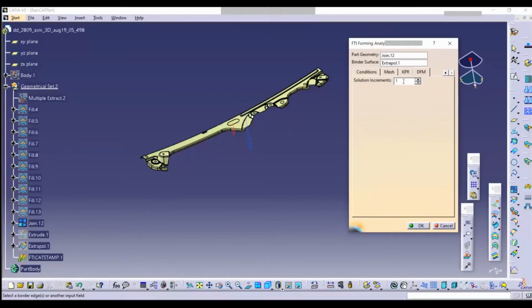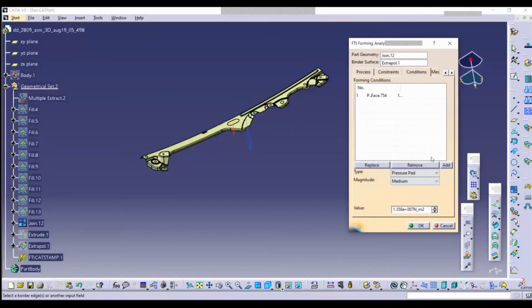And it's going to break up those solution increments into percentages of the ultimate tensile strength of the material for forces to look at various solutions for your blank holder force to try to calculate for you what is the best value to use for that blank holder force. Because one of the biggest questions that typically comes from the conditions is, what value do I put here? So DFM will help you calculate what that blank holder force value should be.